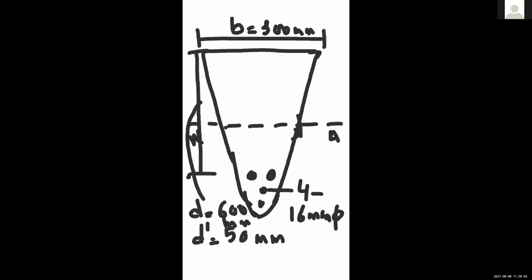In that case, you have to find out the moment of resistance of the beam section and also again determine the reinforcement and moment of resistance of the balance section. First, we have to find out moment of resistance of this section.